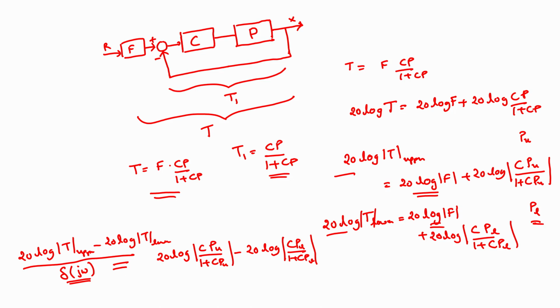So, now that this analysis has revealed to us the division of labor between the feedback controller and the pre-filter, namely that the feedback controller is intended to restrict the spread in variation of the transmission function at each frequency, and the pre-filter is employed in order to achieve the nominal response of the transmission function at each frequency, we shall now proceed with performing the design using the Nichols plot.